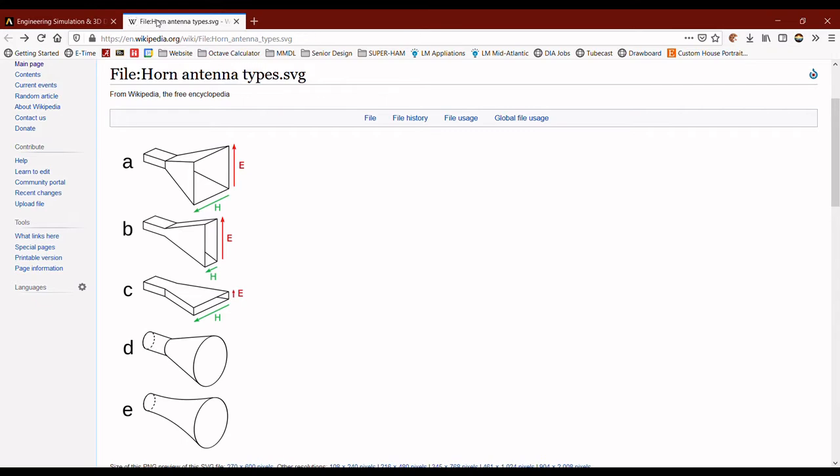Specifically, I will be modeling a cylindrical horn antenna, since they tend to be easier to build, and its rotational symmetry means that it is not an issue if it is mounted slightly off axis. It will operate around 1.42 GHz, since that frequency is of particular interest to radio astronomers.